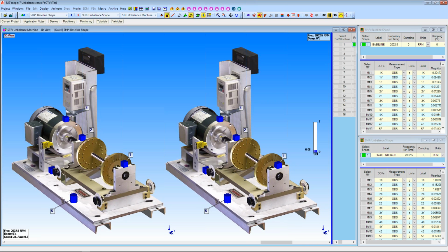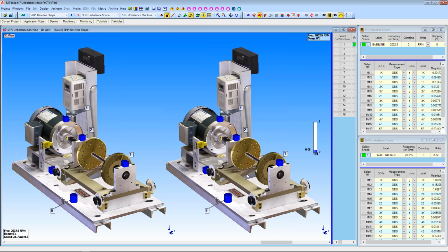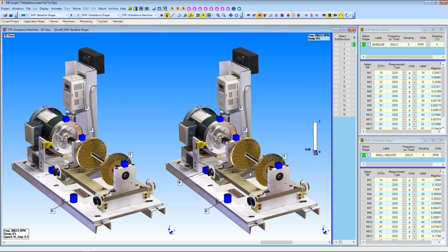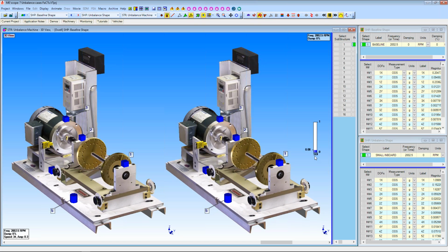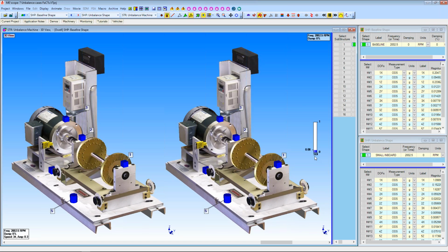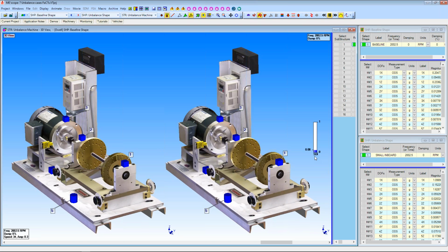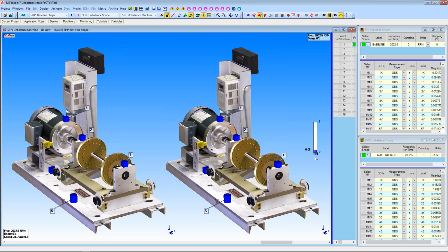You can see the model start to deform, and that unbalance is simply the ODS from the running speed out of the Fourier spectrum of this data that was collected at these points. And notice the SDI here. It's dropped down very close to 0. It's telling us numerically that these are different shapes, quite different ODSs.